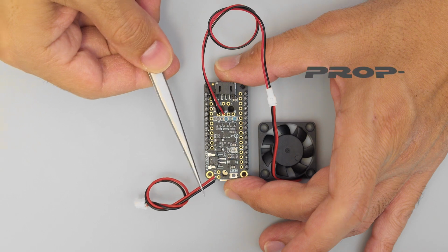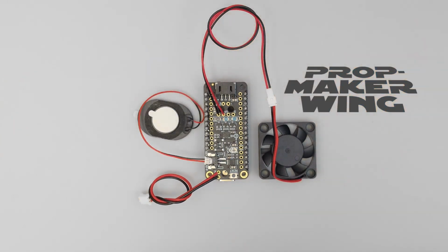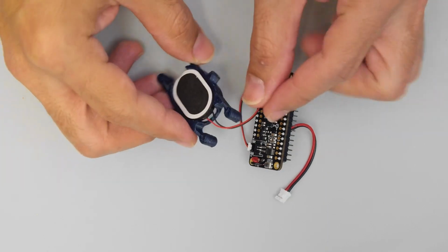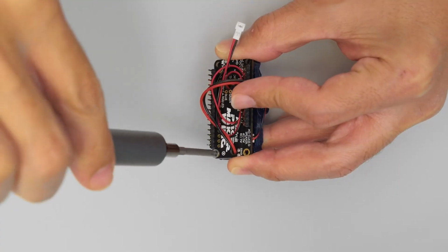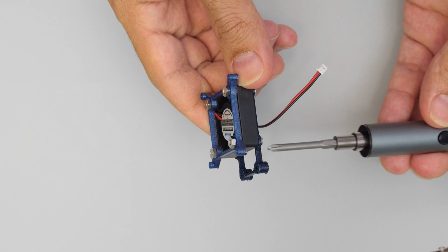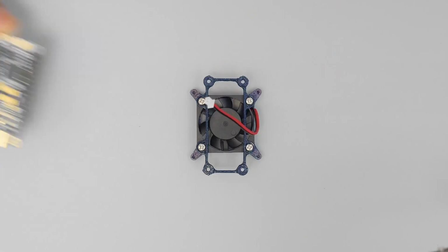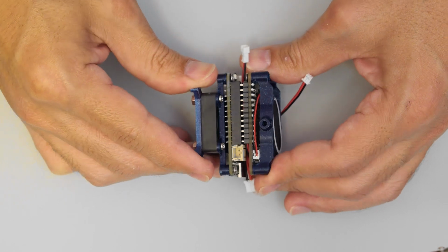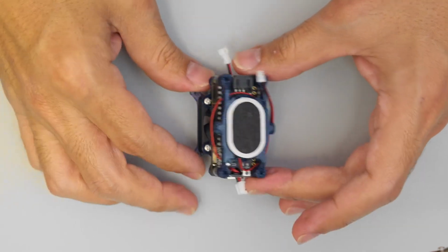We'll start by soldering the various cables and components to the PropMaker FeatherWing. A 3D printed bracket snap fits over the speaker and gets secured to the PropMaker FeatherWing. The mini fan gets sandwiched in between 2 brackets with mounting tabs for securing the feather. Socket headers allow the 2 boards to press fit together to create a layered stack of components.